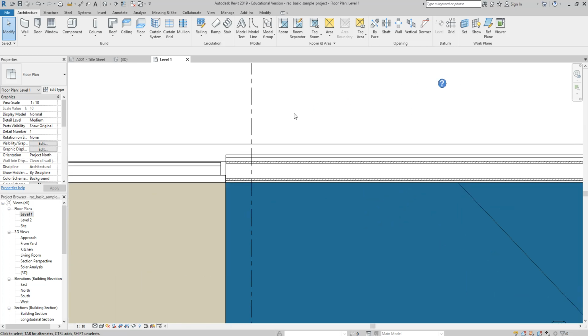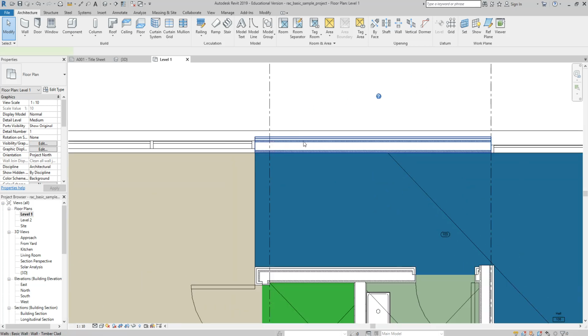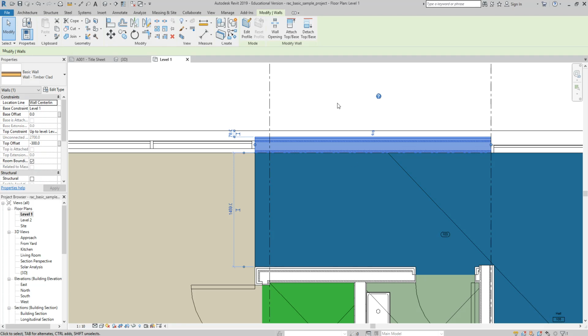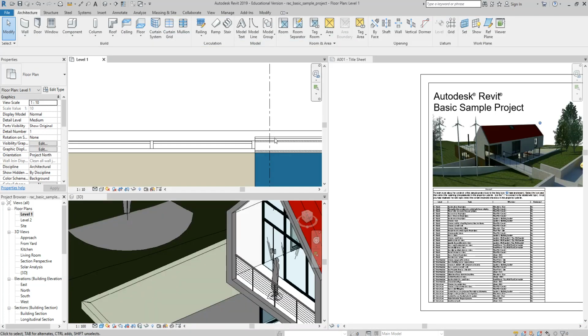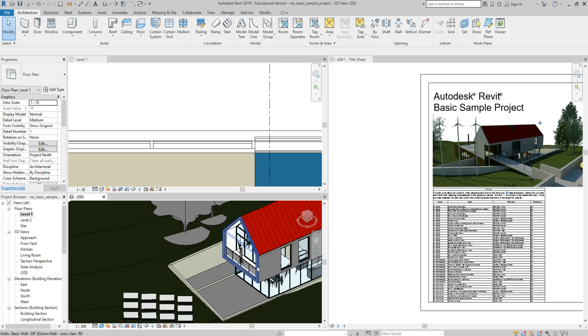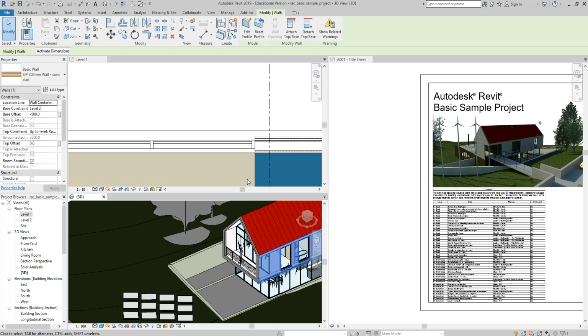How do I know things are walls in Revit? Well, when I look in floor plan view, I can see my wall right there, all right? And then when I go into a 3D view, I can see my walls in 3D, all right? So my walls are three-dimensional objects, and I know it is a wall also because it has a definition associated with it, which is different than AutoCAD. So in AutoCAD, again, if I want to represent a wall, I take one line and I offset it a specific distance from a second line, right? And that kind of implies a wall.